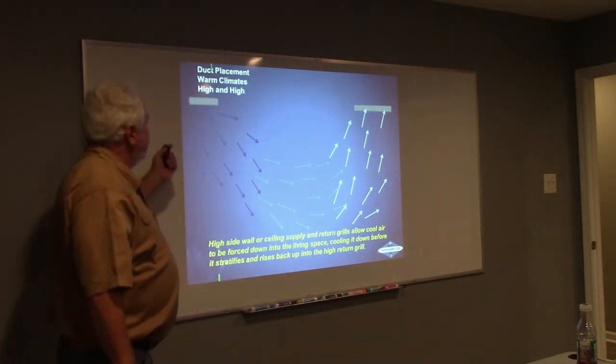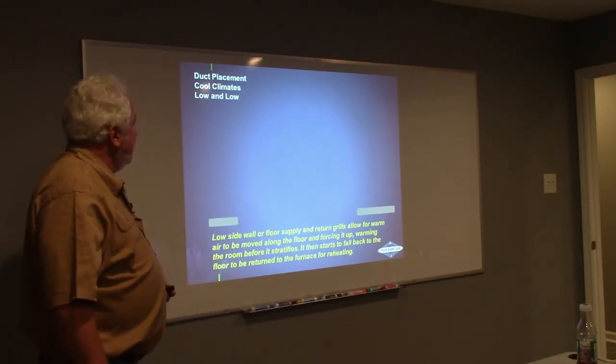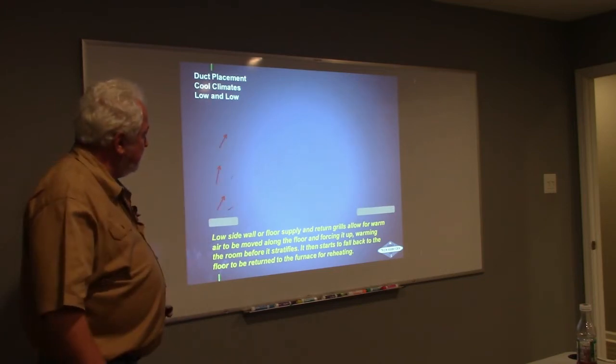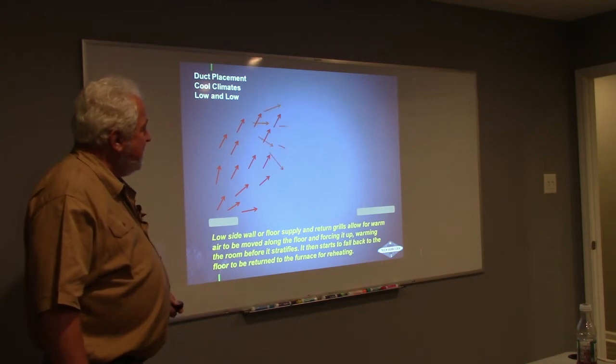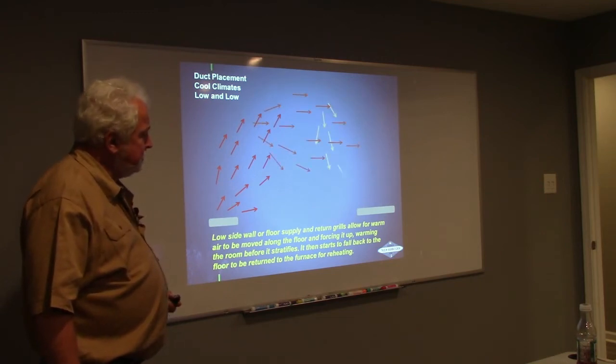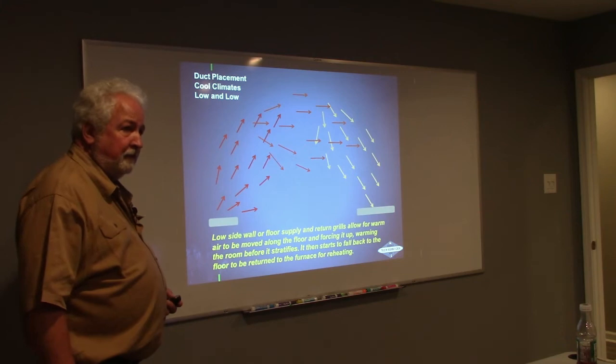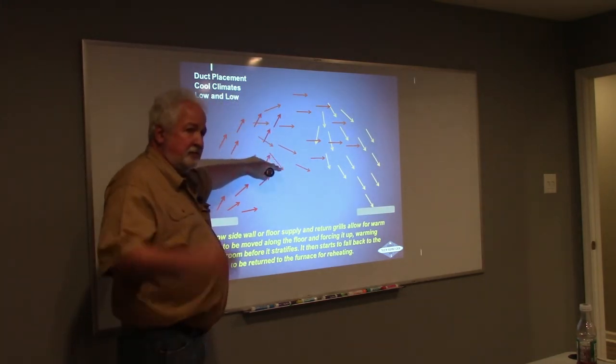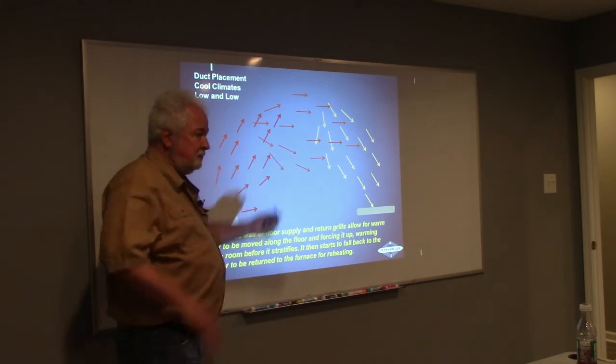All right. So if I had a cold climate where I'm doing heating, I'm going to go low and low. So I'm going to throw the heat up to the top, and what am I going to take off of the floor? All that cold air off the floor. Good. And that way I can warm the building up and have it come down to the face level.